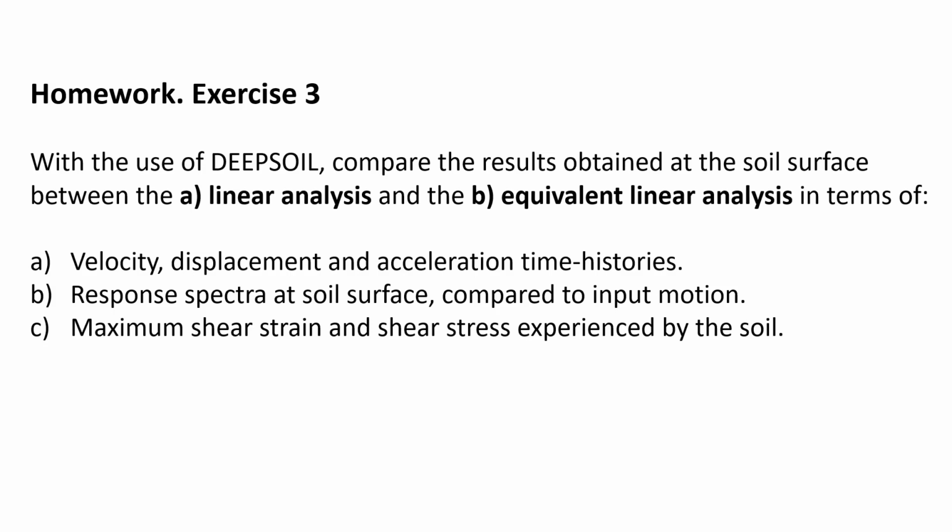and I've included here a series of shear strains and the degradation in the shear modulus and the damping ratio. Those results were obtained from using both resonant column tests and cyclic triaxial testing in the lab at Edinburgh Napier University.